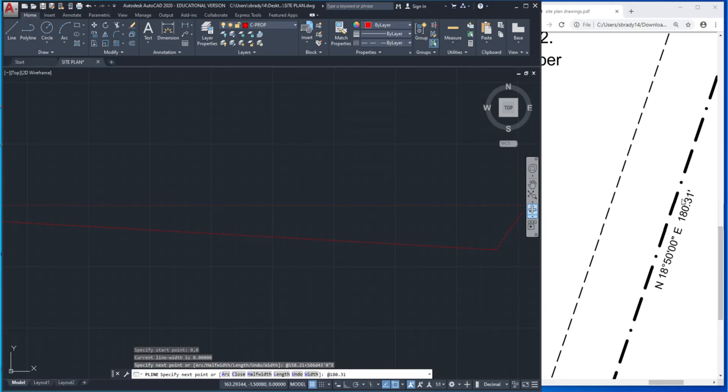And that's a true statement, okay? This little foot mark needs to be left off of your input of surveyor units when you're drawing, okay? The reason it's put there is for architects who are manipulating it, okay? But when you're drawing these, you're going to leave that foot mark off. Don't put it in there, okay? It'll mess up your surveyor unit input.